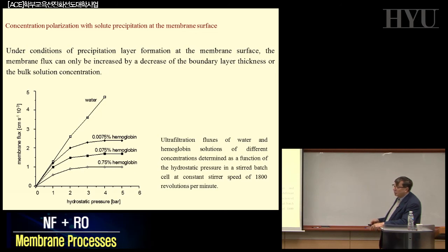From the equation that we wrote for ultrafiltration, you are expecting that increasing the pressure, you increase linearly the transmembrane flux. This result is present, but only for very low increases of the pressure. As soon as you start to increase a little bit more, the flux becomes independent from the pressure. If it's just water, it's linear, so the equation is valid. But when in the water you dissolve, for example, a protein, at different levels of concentration, what is happening? At one point, it becomes constant.